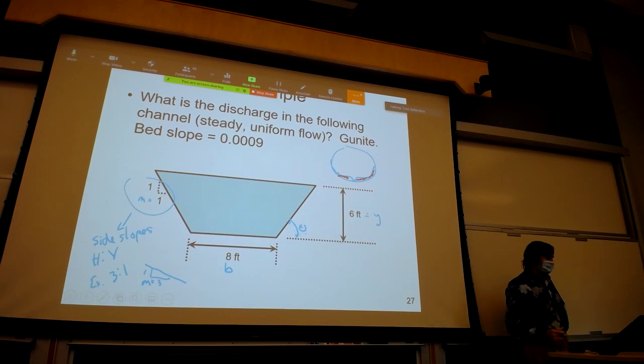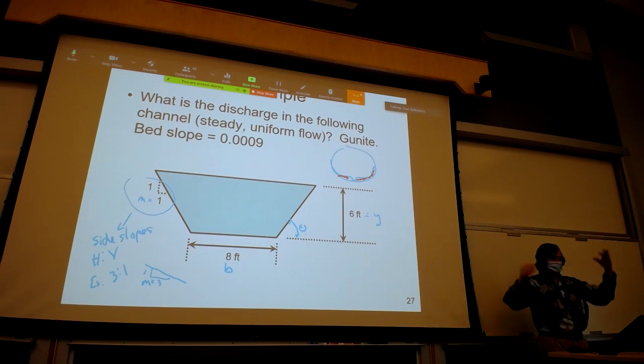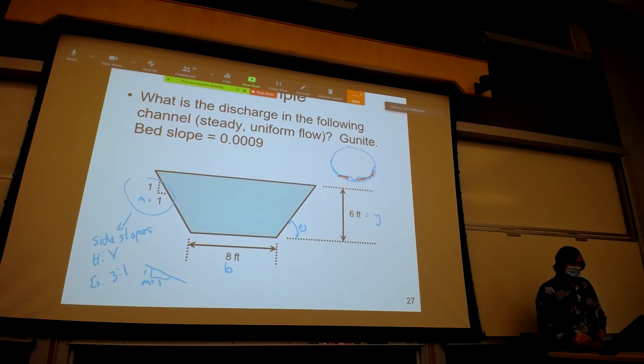That was maybe 3/4 to a foot. So you changed the cross-sectional area, you changed the flow capability, you actually improved the Manning's n, so you really lowered the Manning's n. So after they did this, because of the roughness of corrugated metal, the culvert could actually carry more water than before. But the interstate was never overtopping because you had 40 feet of fill on top of this. The problem was it was too expensive to replace the culvert.